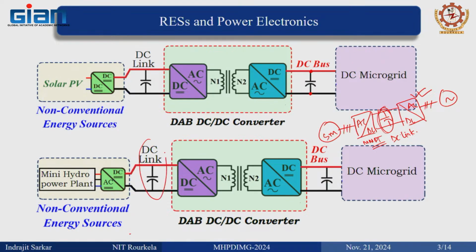So, we need to regulate this DC link voltage, and this is already regulated as it is the DC bus voltage of a microgrid. Previously, with the back to back converter from the grid, we were able to regulate it. Now, we have a DAB DC to DC converter. Now, a DAB converter cannot regulate this output DC voltage if it is SPS.